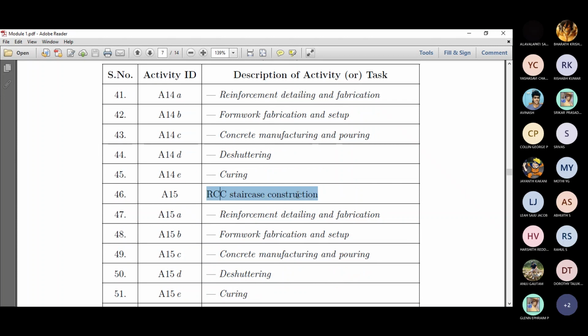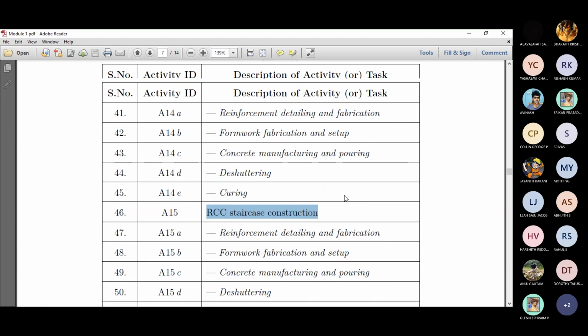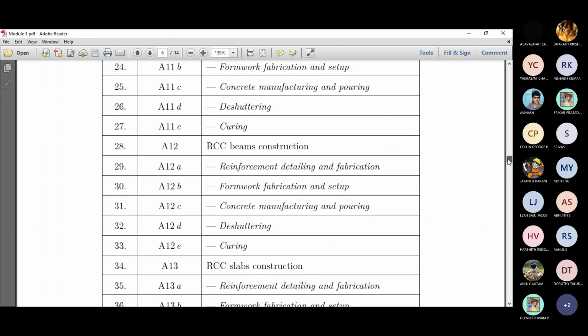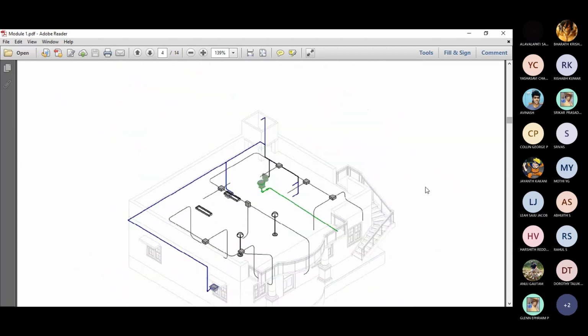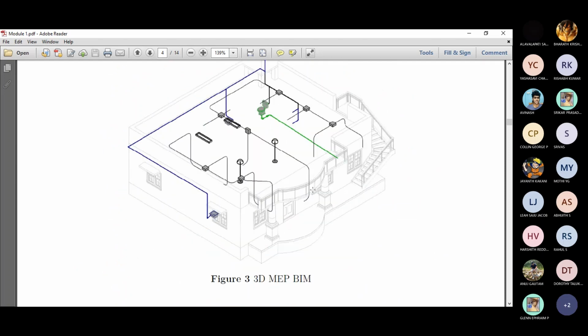And then the staircase. So the staircase here in this diagram, we have given as an external member. Sometimes if you have a staircase inside, you can have a spiral staircase, a steel staircase, whatever it might be. In this case, since it is the external one, we don't have something called a landing room. But if you provide it in the interior, then you have to provide a landing room. So that's the planning thing that you should really do.